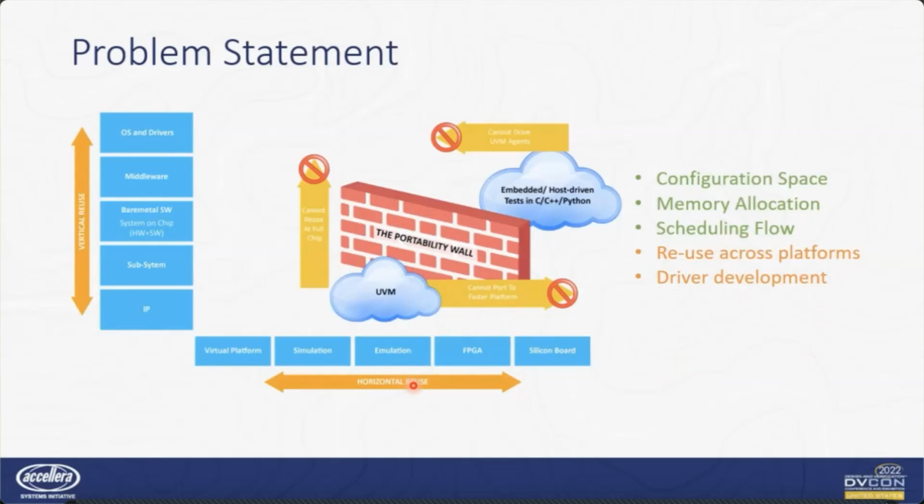So let's say you plan to run your content on UVM and then on embedded cores, then you might use one of these two approaches. The first approach would be to have two separate exec bodies, one for UVM and one for your embedded code. And in the UVM exec body, you basically generate your UVM sequence with your PSS tool.